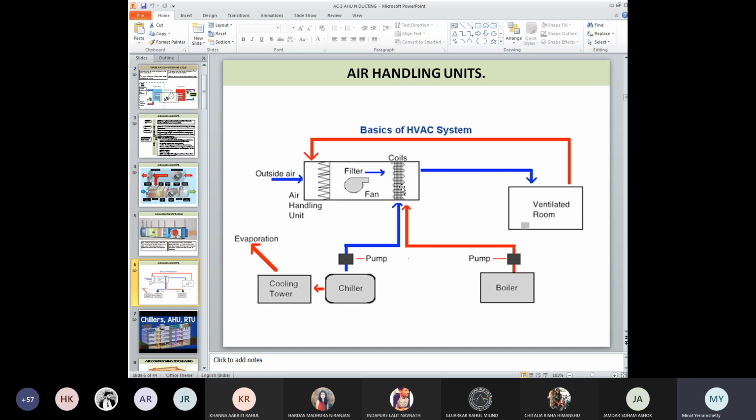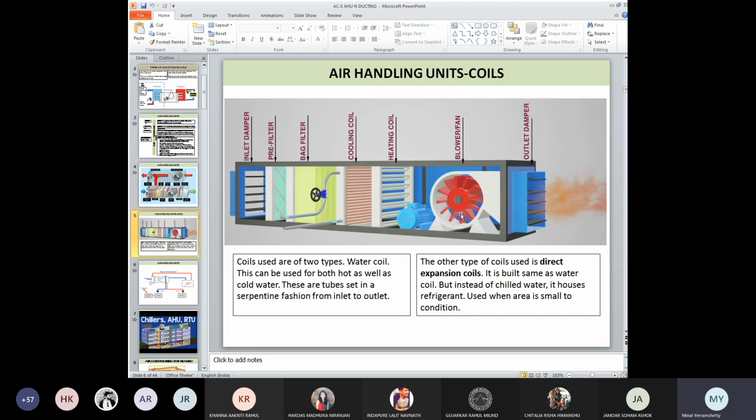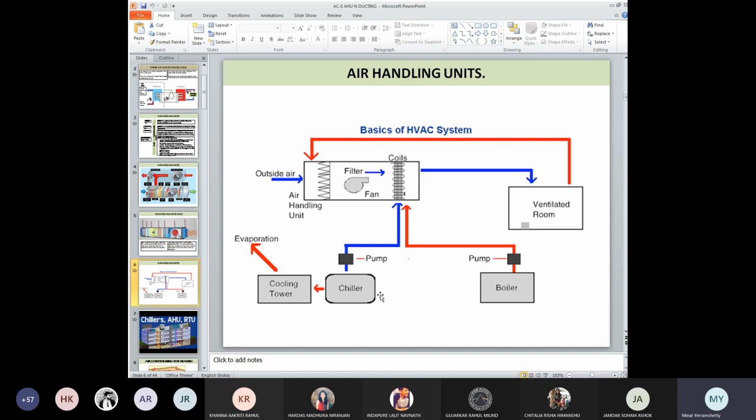I don't need two panels which I showed you in the previous one, where this is the heating coil and this is the cooling coil. Why give? So much space is gone, so much expense, so much maintenance, everything increases. So yes, you can definitely do this. This pipe will come here, this pipe will come here. You put a mixer. अपना shower में कैसा रहता है? You have a mixer, ना? बस वैसे ही. So you allow only the required one to go there. And how will you control it? Do you think at the 25th floor people will go and manually control it? No. You have sensors and they will do it.